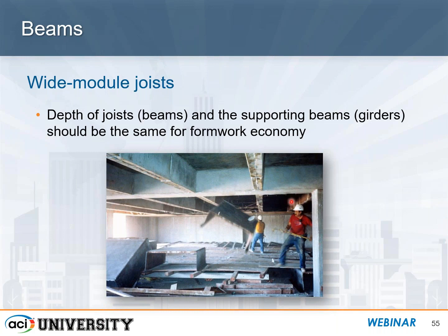The formwork is built for these. Then the forms for the joists, as you see one here, this worker just pulled this one out. Those are at the same elevation, very easy to construct. If you can imagine the beams being deeper than the joists, all of the additional work you'd have to do with the formwork at the intersections where the joists are framing into the girders.